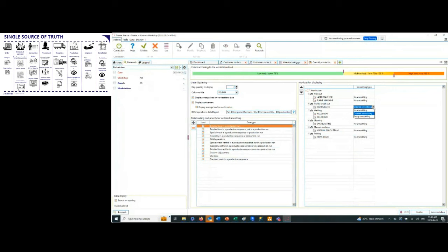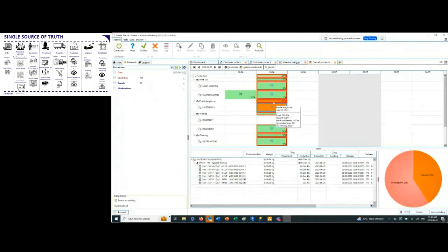Also, it will distribute the workload differently over the course of X amount of time that has been specified per operation, so the theoretical values per operation. What I mean is, if you have a rush order, and you have to execute all operations by tomorrow or else you would have penalties on your project, I could suggest that I don't want any smoothing and I want the machine to operate overnight until all tasks are complete. Now you'll notice that the workload has not been distributed over the course of X amount of days. It's all consolidated into one day.